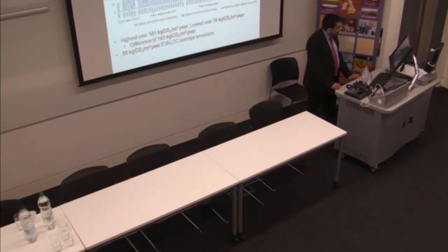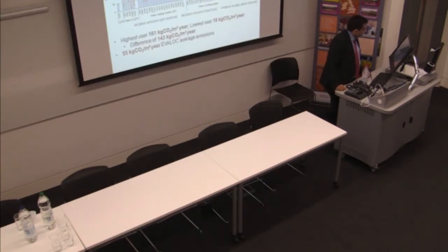Again, in terms of carbon, there's big variation, but 34 are below the national average. 18 kilograms CO2 is very good. Just to give you an idea, the TSB's or Innovate UK's Retrofit for the Future program targeted 17 kilograms CO2 as an 80% reduction target. So there are houses around that as well here. And these are not major retrofits. These are some improvement measures, but a combination of them with a lot of community action and behavior change. So yes, something is happening here.